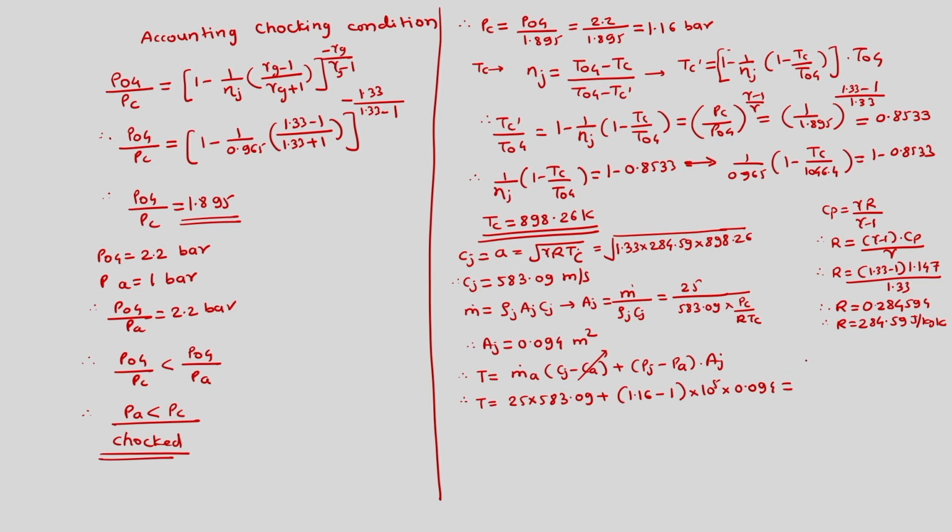This gives us the value of thrust as 16081.25 Newton. This is useful to calculate specific fuel consumption, which is m dot f upon thrust.